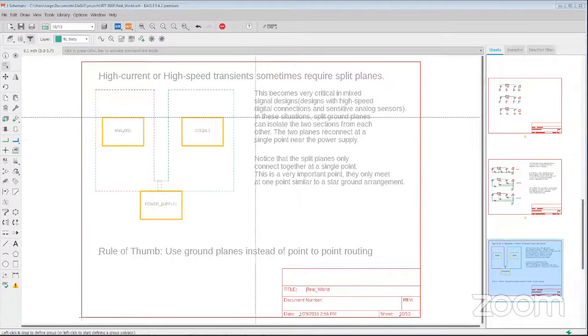For the LCD display, again, it's going to depend on the type of driver that the LCD display uses. So you're going to want to reference the data sheet for the display you're trying to work with. But for sure, there's definitely high speed signals there. There's a lot of data that has to move very quickly. So definitely you're going to be very concerned about your signal quality and making sure that your lengths are well matched and all that.